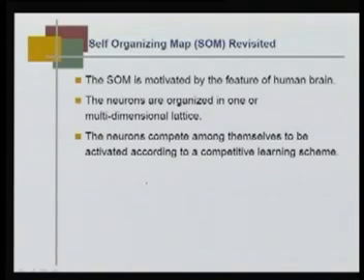What I just told you is that camera calibration helps us to find out the camera model, so that given x, y, z in the actual world coordinate, the camera model helps me to find out what should be xf and yf, which we also call u1 and u2. Okay.